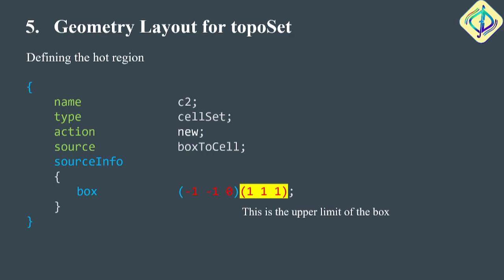Okay, so say if my geometry was only up to say 0.9, I can still use -1, so I can go beyond that point as well. topoSet will understand, OpenFOAM will also understand that you have to engulf that entire geometry and it will assign it accordingly. Okay, it's only when you are doing something that requires it to be smaller than your geometry, that is when your bounding box or the limits that you set for this box will be very sensitive. Okay,